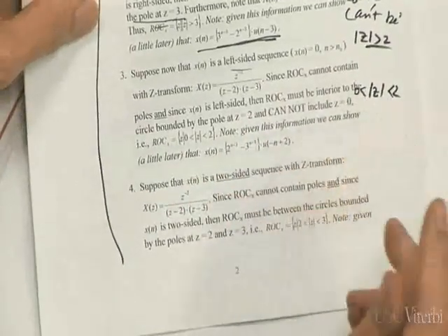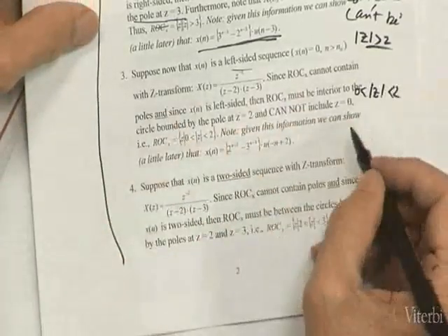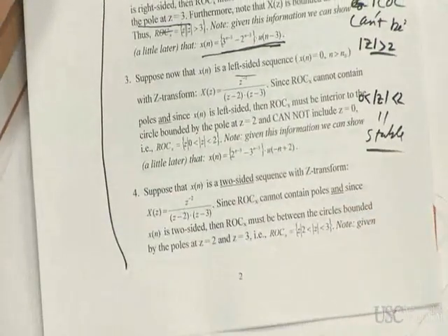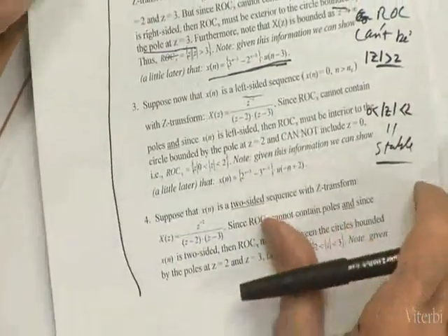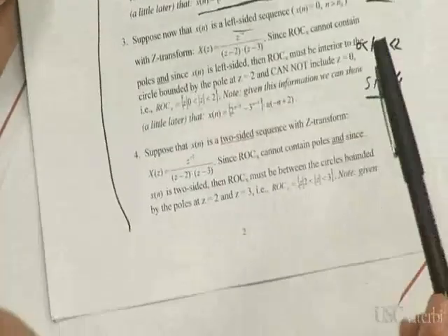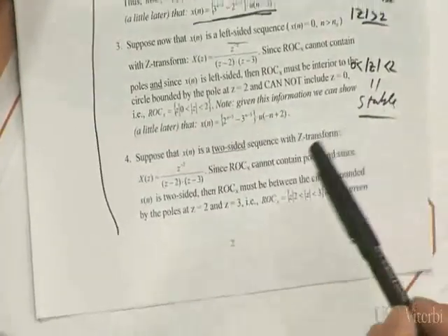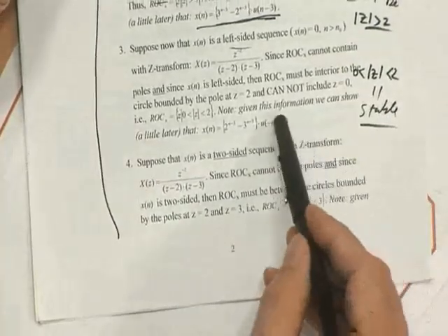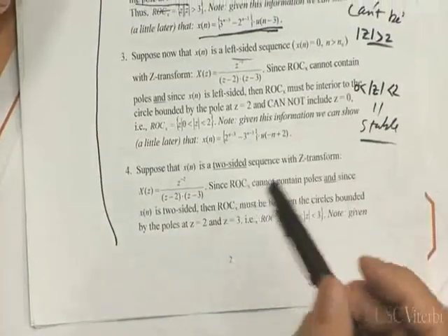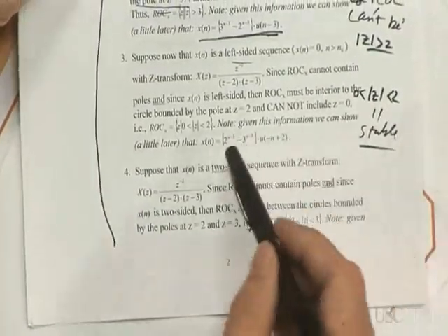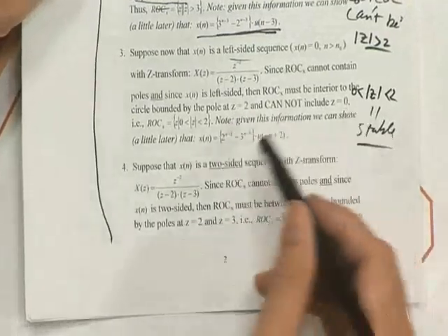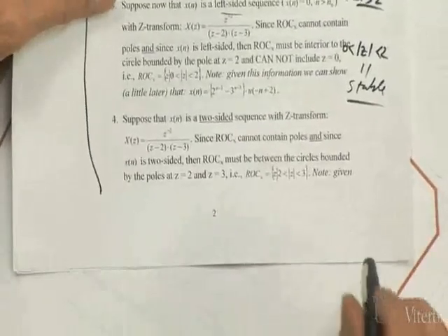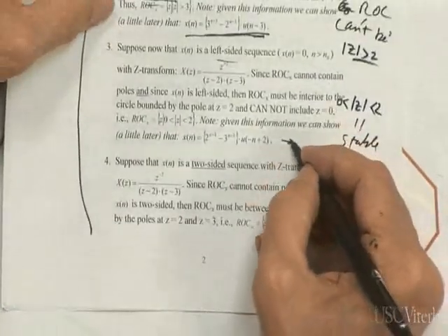Well, one thing it tells you is that, as I said earlier, it must be stable. Whenever you find the inverse Z transform, it better be stable, or if it isn't, you didn't find the right one. And in fact, this is the result for the inverse Z transform. It looks like this, kind of the same form, except instead of u of n, it's u of minus n plus 2, which means that n is negative. So these, what seem to be positive powers of n, really are negative powers of positive values. So sure enough, that goes to 0, as you would expect.